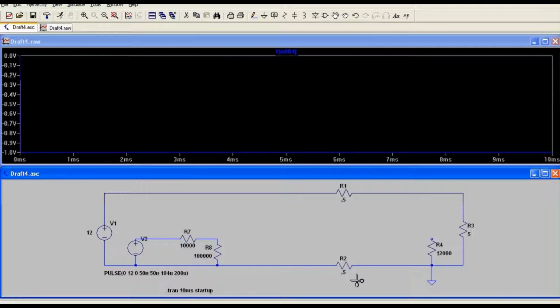And so it's really like just measuring between here and here, if that makes any sense, as if between here and there was a short circuit, more or less. So that's why you end up seeing -1 volts when you're pulling a lot of current through that load, and you end up with a voltage drop here. And that's only happening because we're using that as the common return for both these light bulbs and the signal.